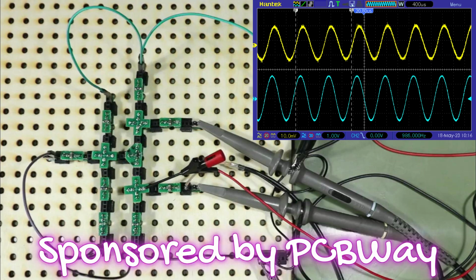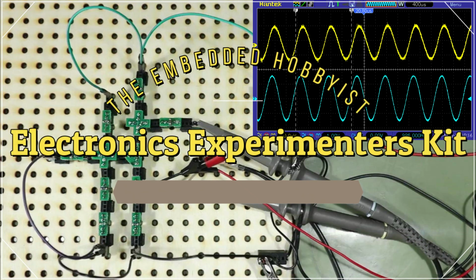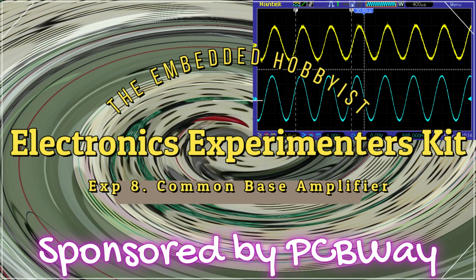And welcome back. In this video we're going to look at the common base amplifier configuration. This is not a commonly encountered configuration as the input impedance is very low, used more in RF amplifiers where it's common to find low impedances.